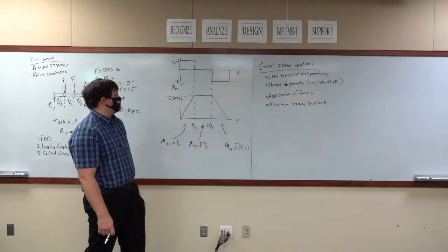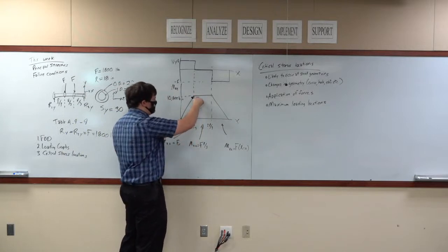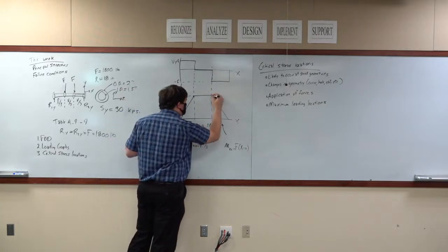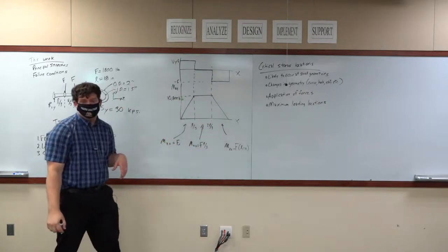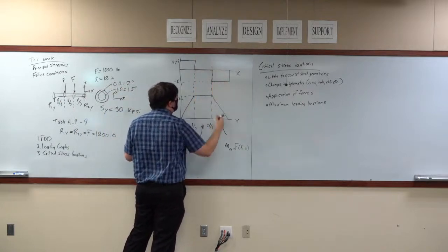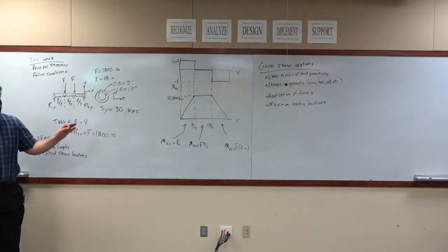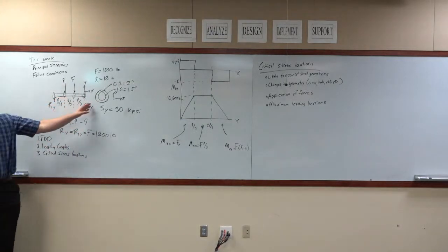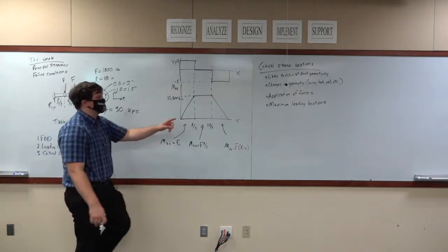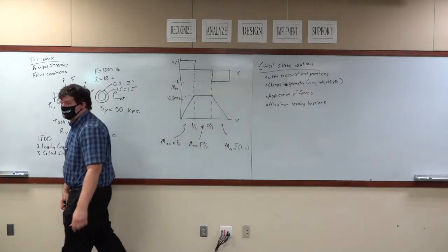So we're looking directly at the lines. Well, I can say right here, this moment value is basically its maximum. And same right here. It's basically at the maximum. And at that location, this shear force also is at a maximum. So, not only are those 4 critical locations defined by loading, not only are they important for determining critical stress locations, but it turns out that's where the maximum loading occurs also.